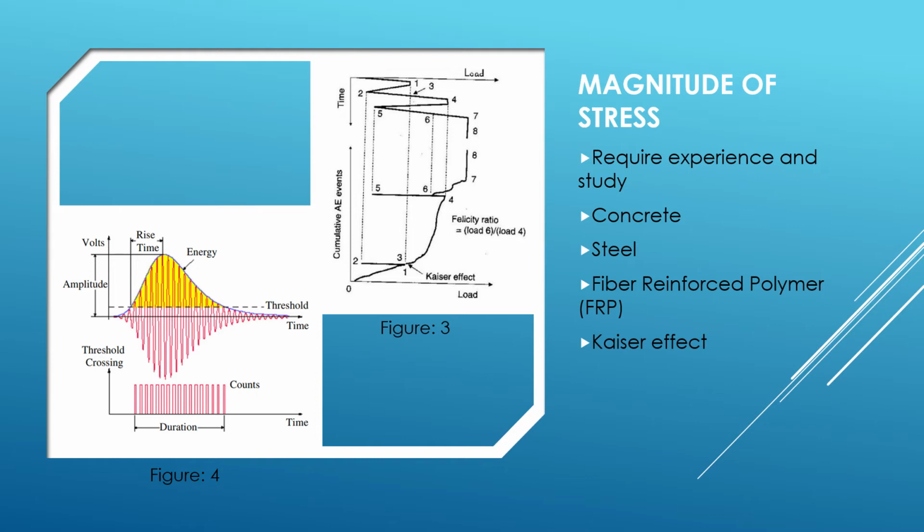Materials found on bridges under a load are known to emit acoustic waves only after a primary load level is exceeded. This is known as the Kaiser effect and is represented in Figure 4 on points 1, 2, and 3. All of these conditions, as well as many more, are to be considered while analyzing the data received from the sensors.